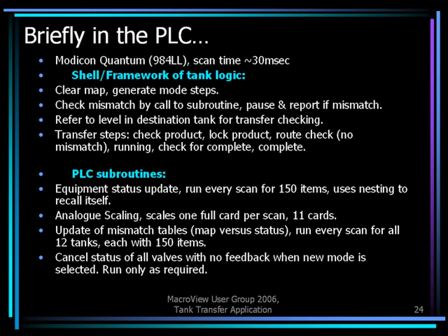Okay, just briefly about the PLC. We're here to talk about MacroView, so I won't dwell on the PLC too much. It's a Modicon Quantum. It's running fairly fast, roughly 30 milliseconds, doing all of this work. We've got a shell or a framework of tank logic only, so it doesn't know anything about really what it's trying to do. All it's doing is checking status against the map, updating status for the equipment, and determining if it should either continue or stop the process it has been asked to run.